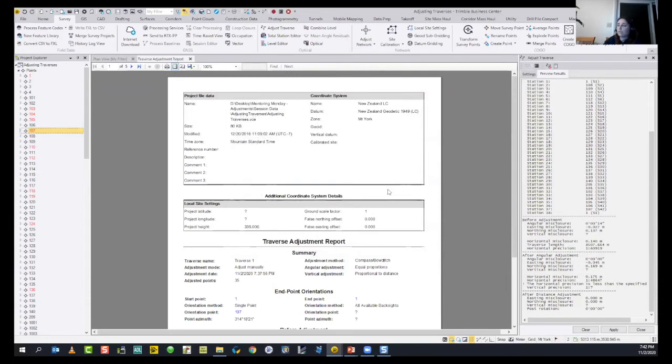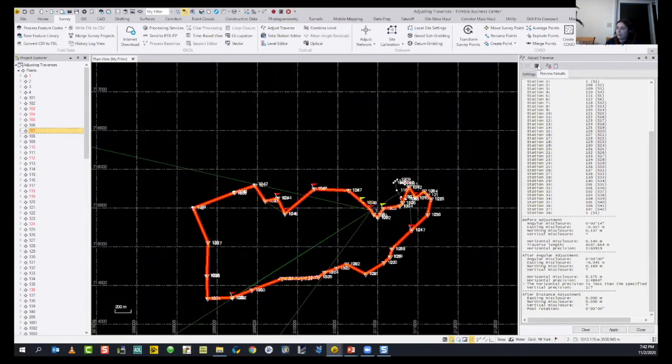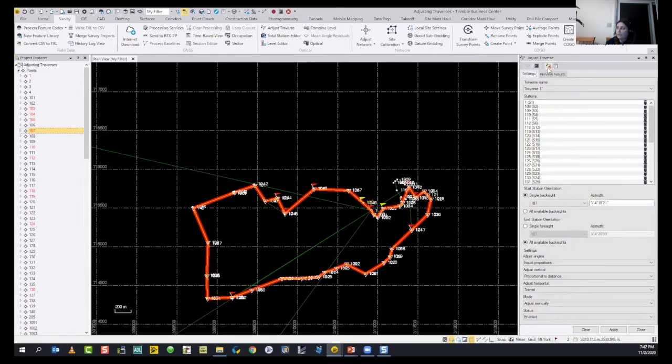It's also possible to customize it. If you aren't satisfied with the results, you can always come back and disable this traverse and start creating a new one, or you can just clean up all the stations by clicking the first station, start station, and come back to the beginning under the same traverse name and create a new one.